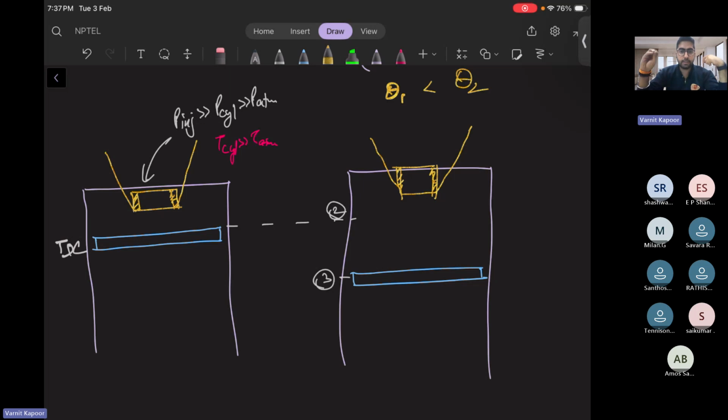That's why the heat was added at a constant volume, because the air-fuel mixture was already inside the cylinder. But here you are supplying the fuel, and when you are supplying the fuel, your injector pressure is constant. Suppose the injector pressure is higher than the cylinder or atmospheric pressure, say 10 bar of injector pressure. I'm just taking an example. So the fuel is injecting at a constant 10 bar of pressure.